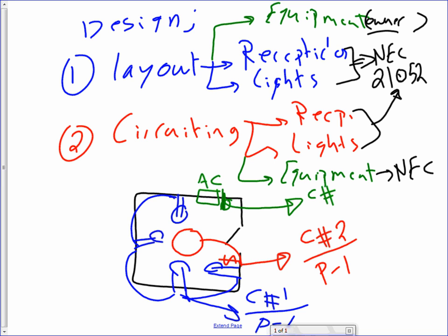Adjacent odds. So the panels sit like this, guys. Here's your adjacent odds, here's your adjacent evens. This is 1, 2, 3, 4, 5, 6, 7, 8, 9, 10. These are 10 circuit breakers in the panel. This 1 and 2, that's how they label. 1 and 2 are both 120. 3 and 4, 120. 3, 4, 5, 6, also 120 to the neutral. You can't take 240 between them.